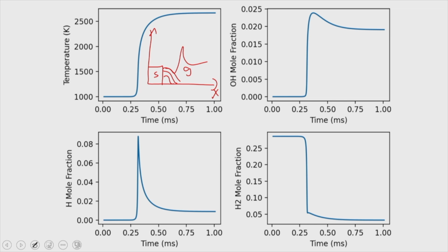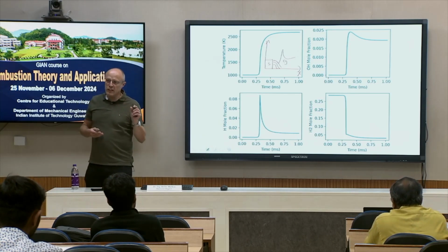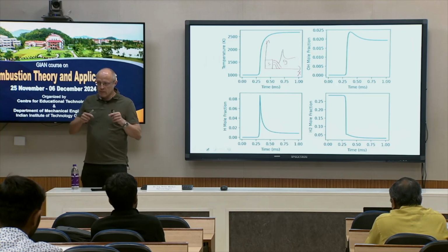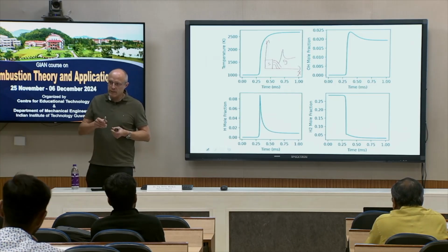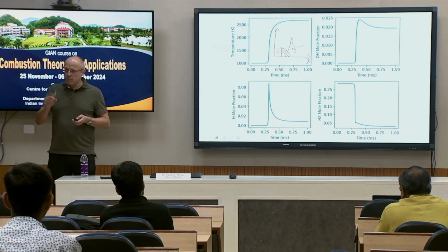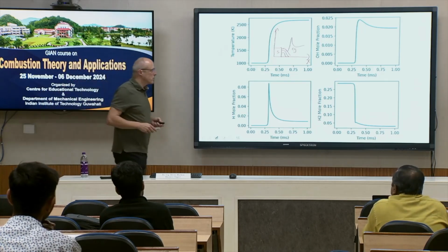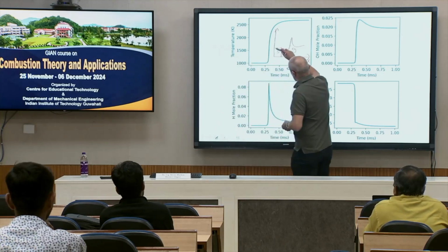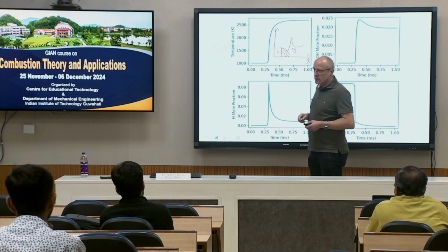Because for most of the solid fuels we have, the combustion takes place in the gas phase. So they vaporize, and then combustion takes place in the gas phase. There are very few compositions where you have direct burning of the solid phase. So that's the simplest setup. You define your solid phase, you define your gas phase, and reaction take place in the gas phase, and then you can also include some wall reactions.